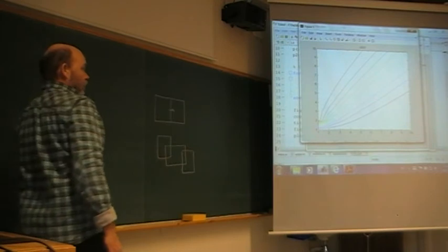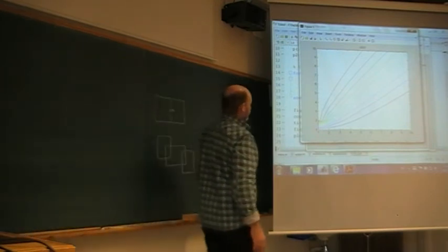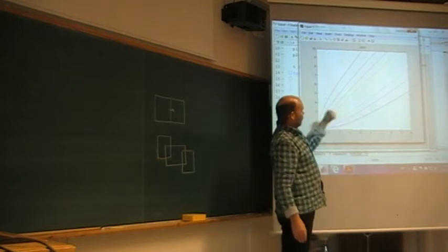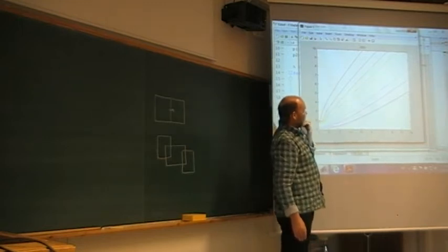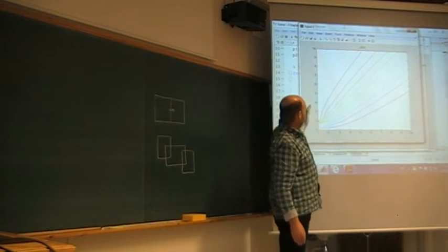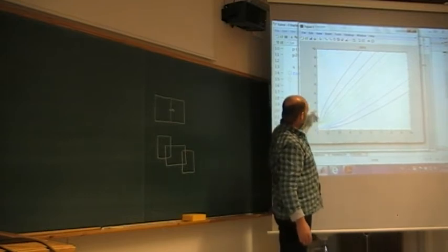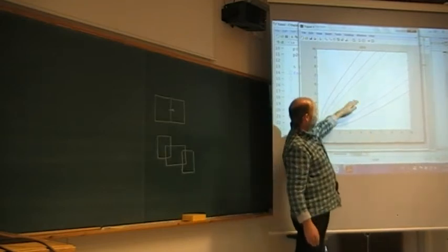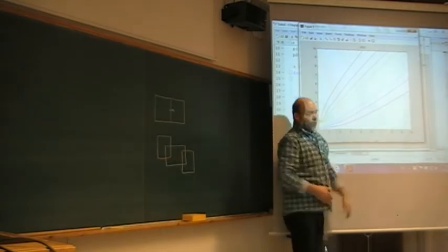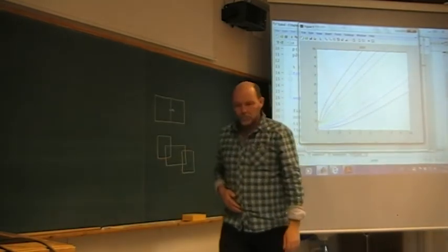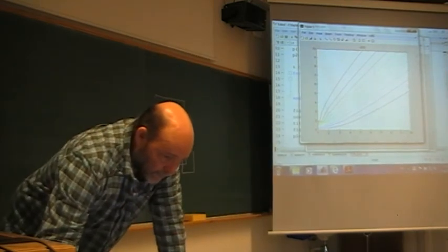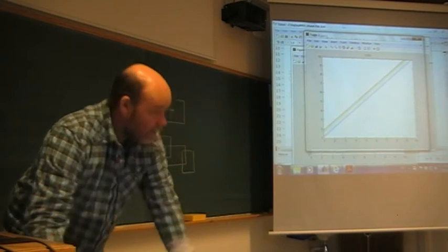This is a solution from the first order upwind scheme. So the iso lines here now describe the unknown quantity phi, which was 1 here, and then a gradient from 1 to 0, and here 0. And you see really the smearing out is quite strong. With a central scheme, it's actually possible to get this one.